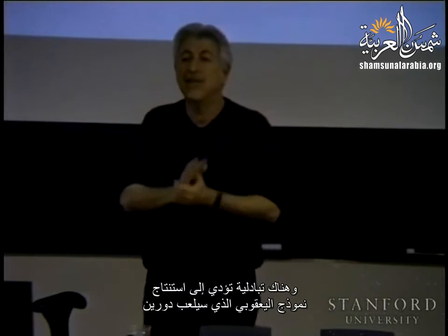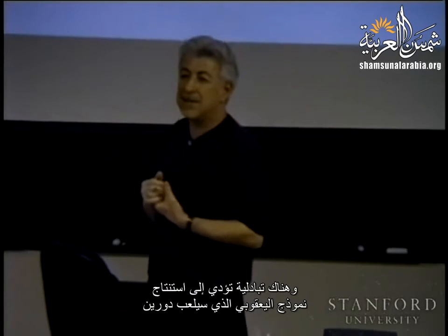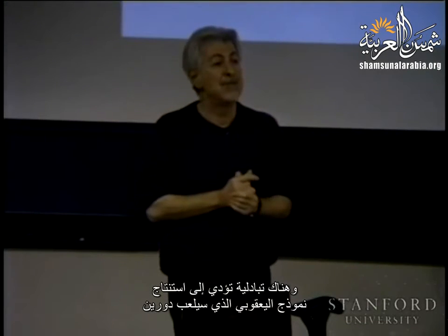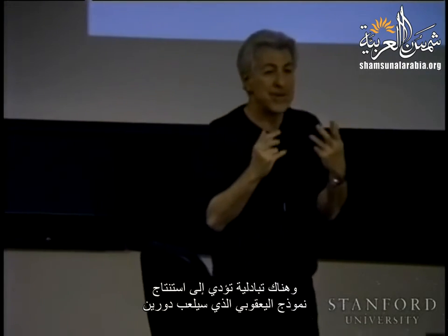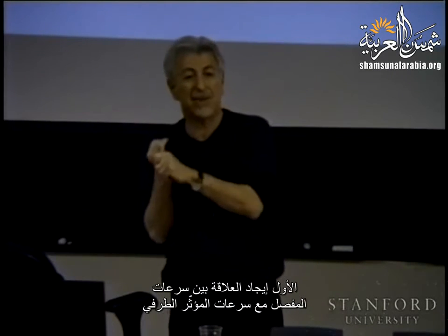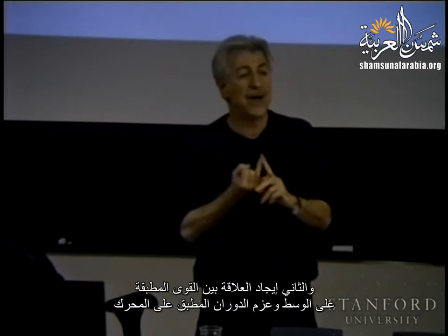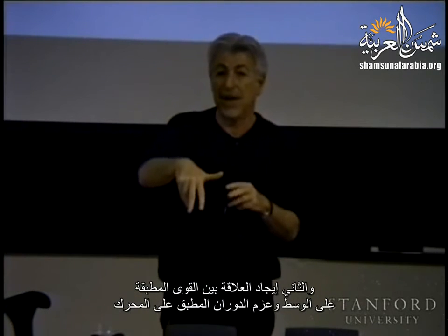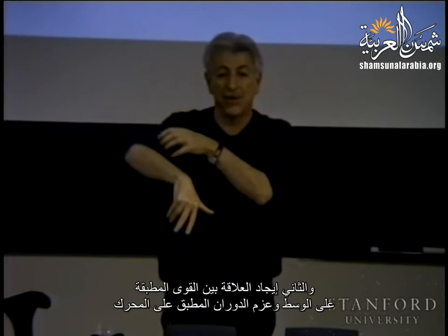And there is a duality that brings this Jacobian, the model that relates velocities, to be playing two roles. One, to find the relationship between joint velocities and end effector velocities, and one, to find the relationship between forces applied to the environment and torques applied to the motors.